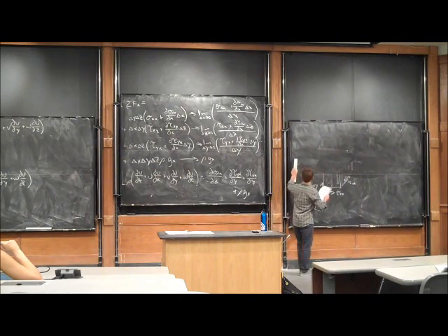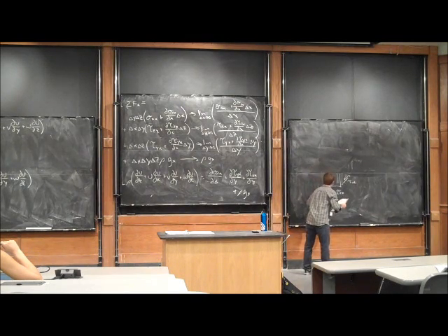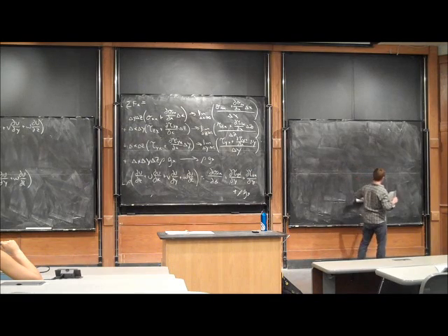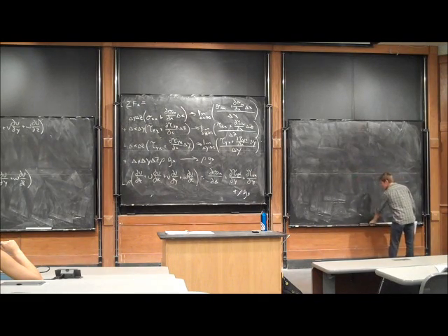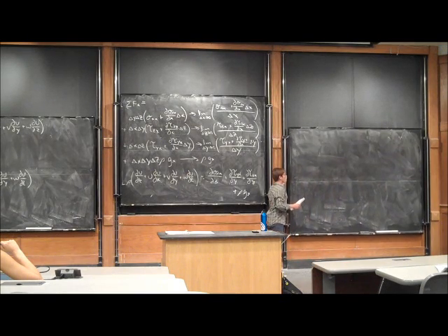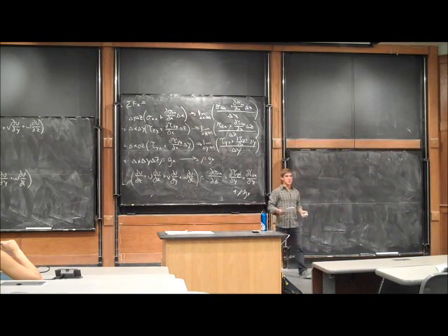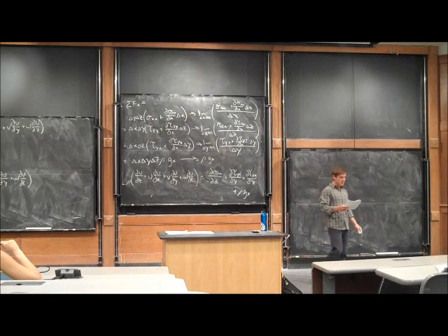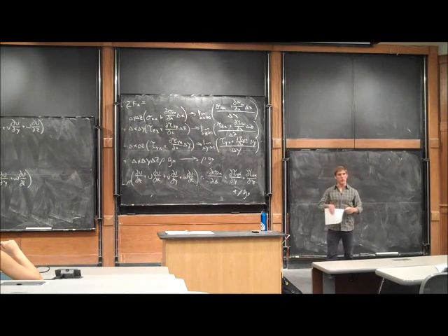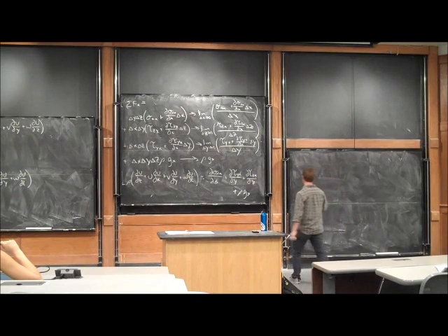Those stresses arise from two different sources when you're working with a fluid field. We have the stresses working on the fluid element due to pressure, which is your hydrostatic pressure due to your depth in the water. And we also have the viscous stresses, which dissipate energy due to the shearing of layers of fluid against one another.